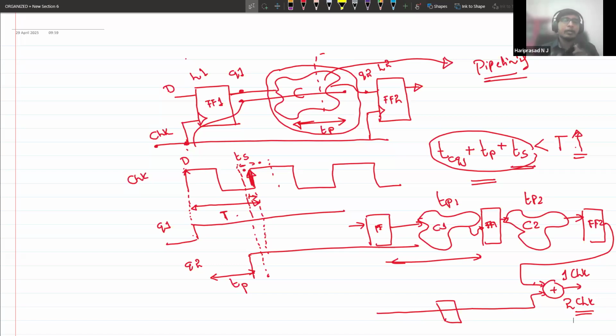Especially we will be coming to that point. We have something called CDC, right? Different clock domains. Let's say I have a higher clock frequency and another lower clock frequency. Whenever I want to interact between these two clocks, that also is usually treated as a timing violation. But there are some synchronization techniques where we can resolve that timing violation. In such scenarios we will be putting those constraints, and I'll tell you how to do that.